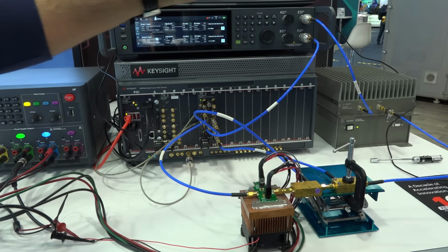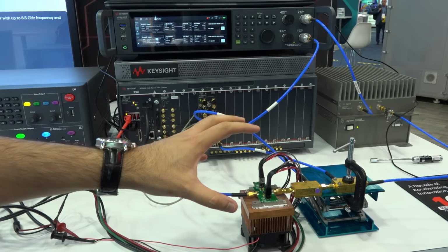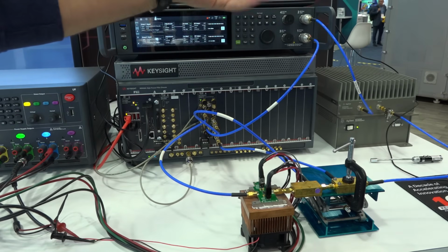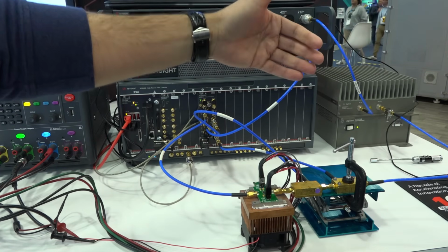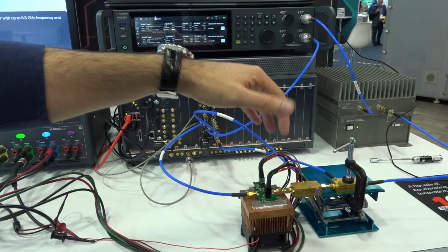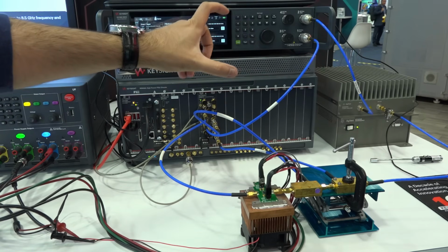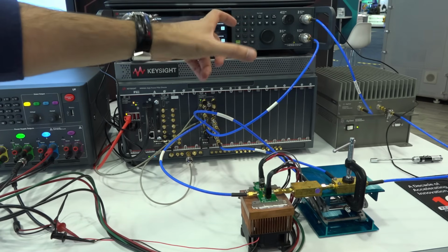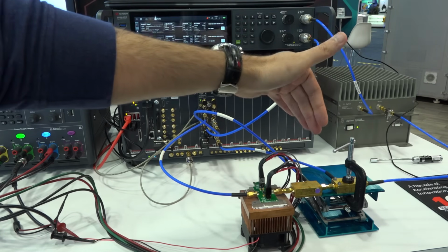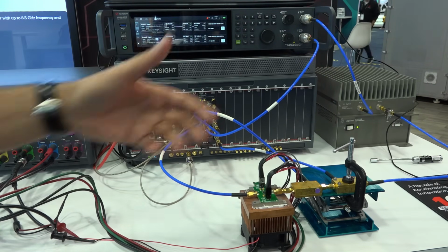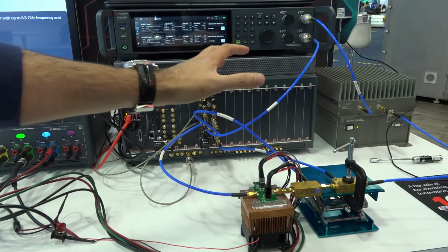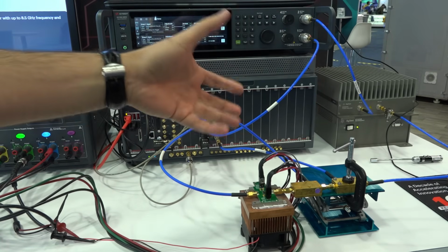So now imagine that I take one channel and I put it at the input of an amplifier, and I take a second channel, pass it through an amplifier and a coupler, and I feed it now to the output of my DUT. So now by playing with the waveforms and having the correlation and coherence between them, I can synthesize any impedance I want at the output of my amplifier. So now I have complete control over the load pull. Now you have this, now what can you do with it?